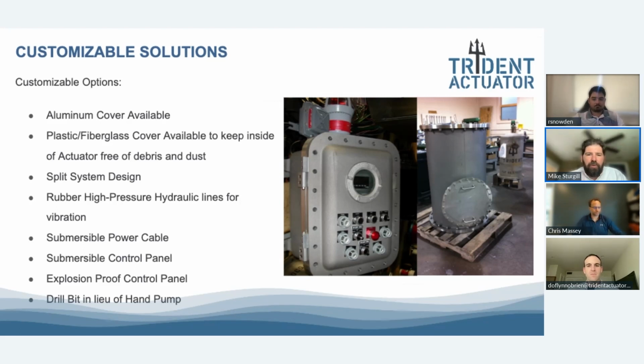And then if you really want a submersible actuator, submersible panel, obviously we'd give you submersible cable. And as I showed you that hand pump, we can do the drill bit. I know a lot of end users that do the maintenance on these have battery powered drills, and so we can do that. If you want more stored energy, to be able to maybe open and close, whatever the sequence is on a fail safe, we can also add another accumulator or a larger one. So a lot of different options, whatever the end user wants.